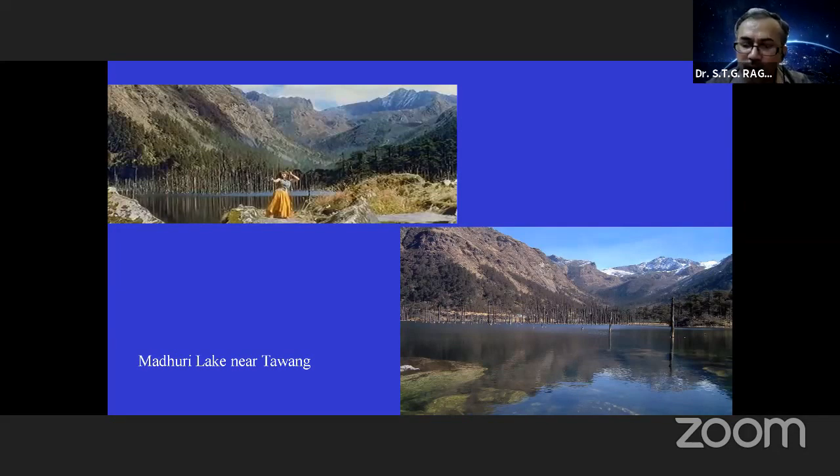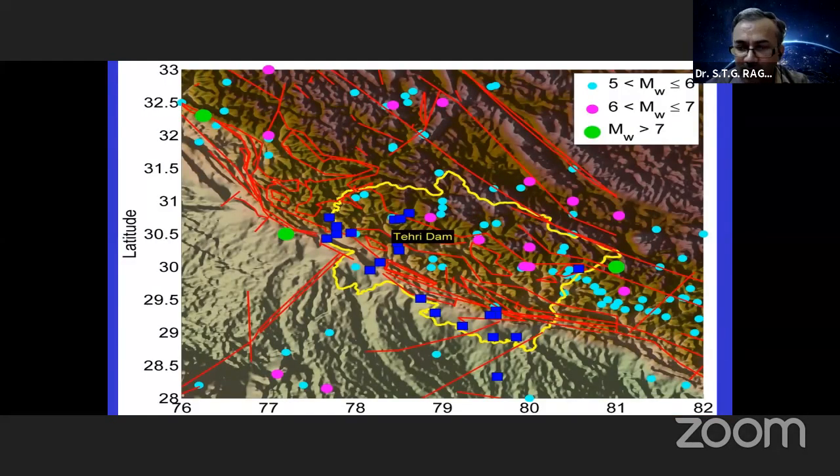Now I have shown you, you see, this near field ground motion is very, very important. Now in Uttarakhand and Himachal Pradesh, they are building several dams to capture hydro power. Many dams are built on top of the faults. In the Himalayas there are several faults, and below the dams many faults pass by, some within 1 kilometer, so you have all these near source features.